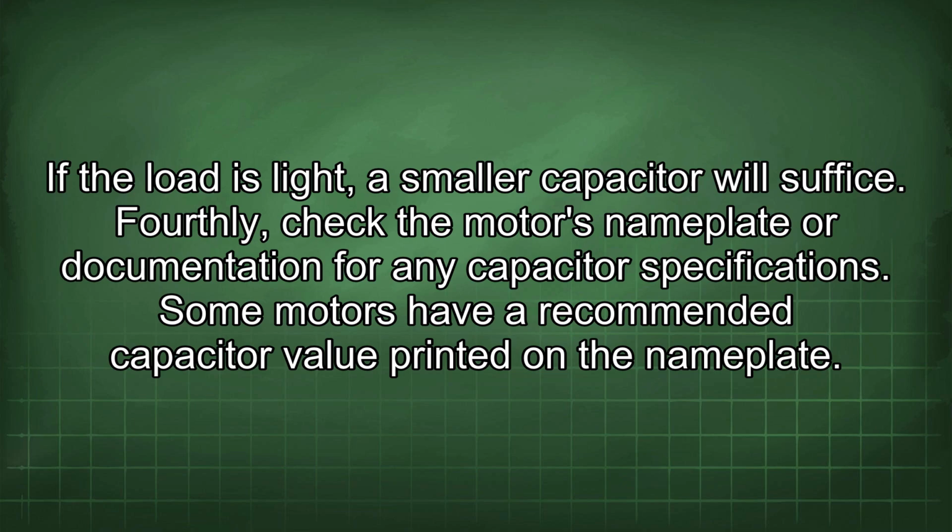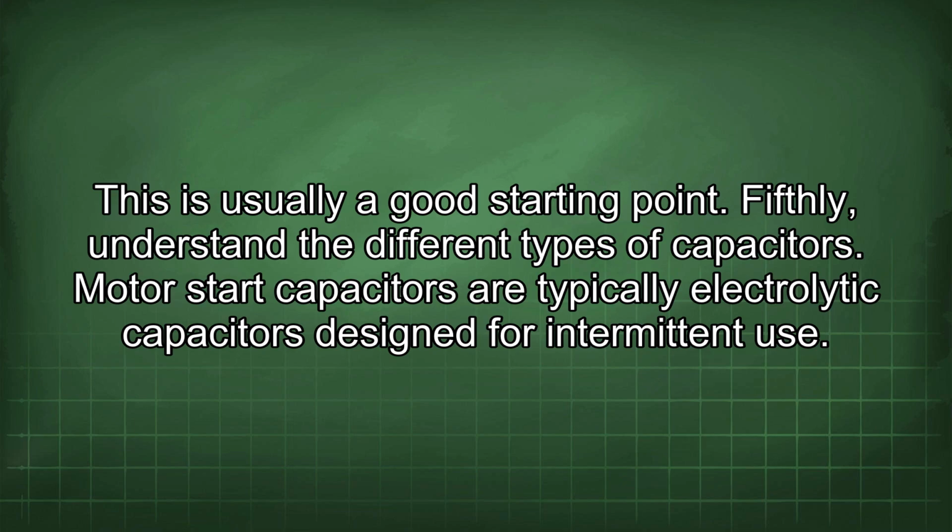Fourthly, check the motor's nameplate or documentation for any capacitor specifications. Some motors have a recommended capacitor value printed on the nameplate. This is usually a good starting point.